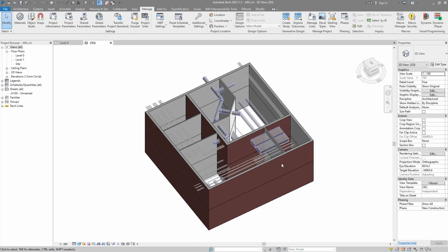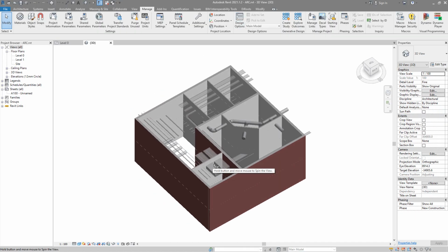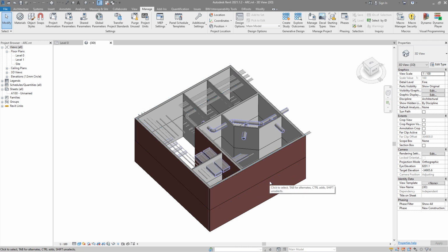Okay. And now different project units. So now I'm in this 2021 Revit, and here I originally created this script. When I tried to find what could possibly create errors on Alexander's side, I found that by using some project units which are different from the units which I used while creating the script, you can have strange results. I mean, results will still be there, but it will look just funny.